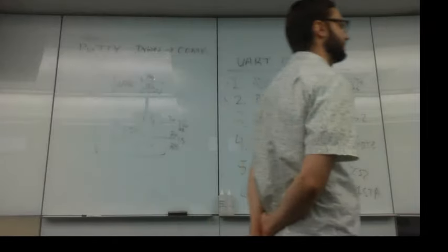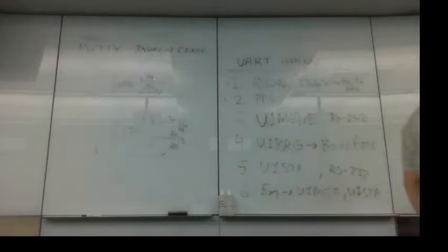Okay, so RS-232 in the PIC has this block diagram. Basically, you write to the baud rate generator, and that sets everything up in the hardware. You have a UART receiver and a UART transmitter register, and those send and receive things on those pins. You can set up flow control for the request to send and clear to send pins. You have to set up those pins though.